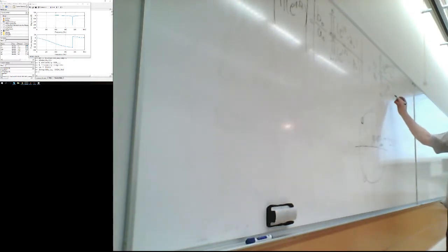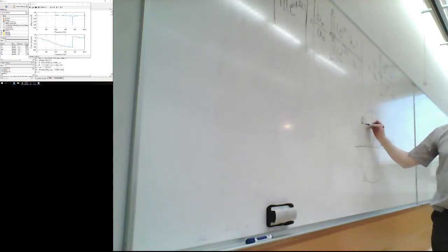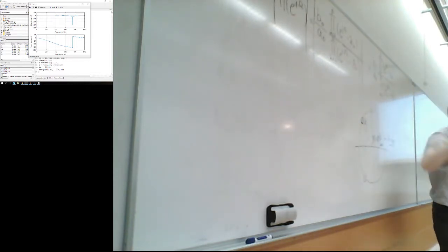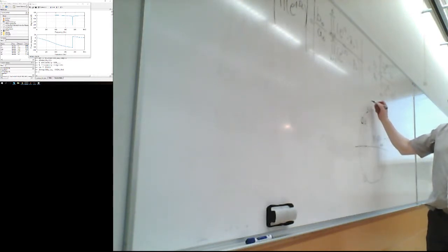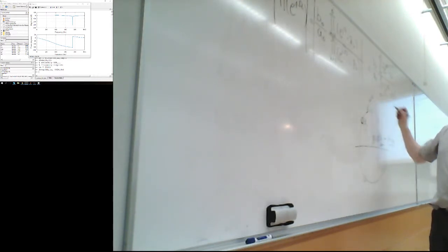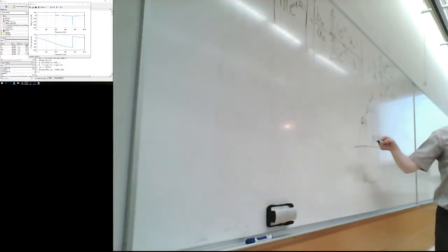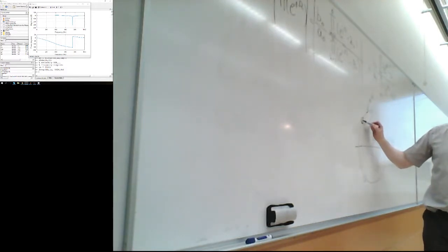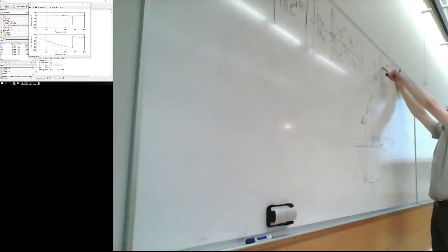So on that frequency, we actually hit the unit circle. The distance between that point and the zero is 0. Remember, we are talking about the point e to j omega here, and that's moving on the unit circle. When it hits that point, this distance becomes 0.